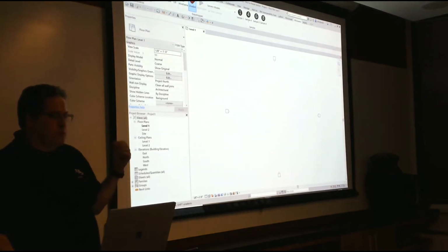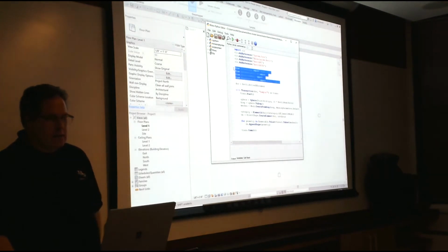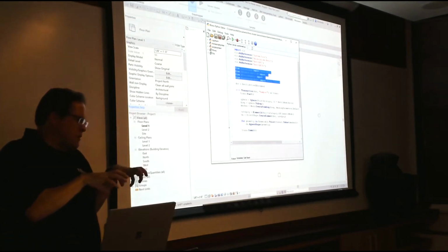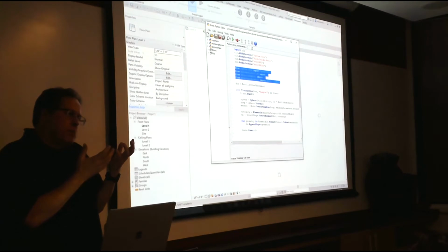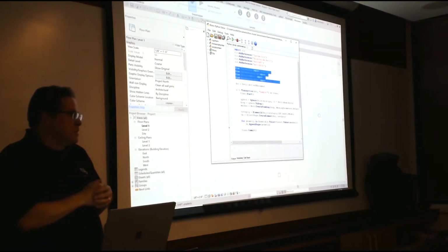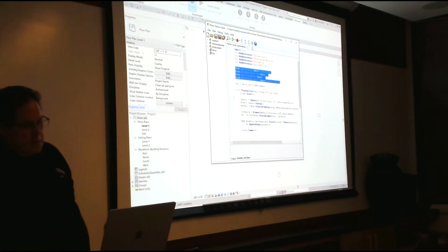What's interesting for those 3 Python people in the crowd is that we can access the Revit and the Rhino SDK in the same place. There's no difference. They're both running here. This is something we did in Rhino 7: we pulled Rhino 7 apart into pieces, so it can be loaded inside any other Windows 64-bit application as a DLL. So this works in BricsCAD, ArchiCAD, Unity, Unreal, and AutoCAD. But today we're looking at Revit. So anyway, we can look at both SDKs at the same time.